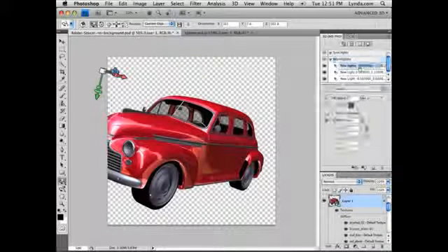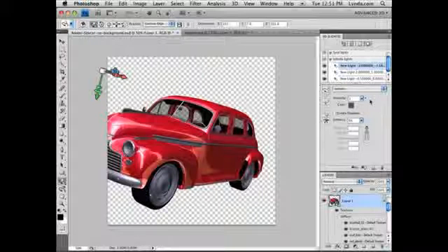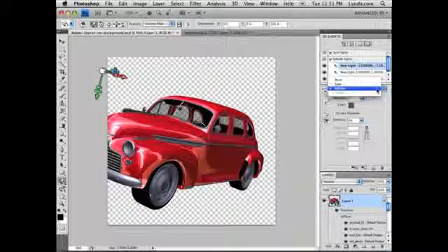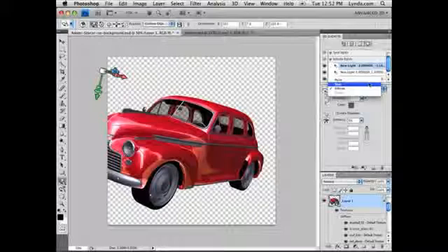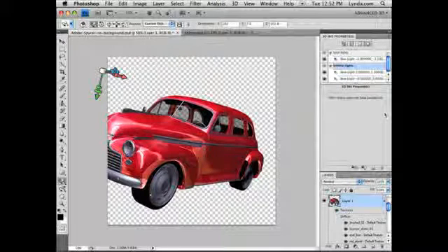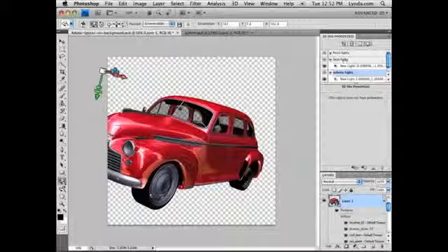Even though this light was created as an infinite light, the type of light can still be changed. To change the light's type, I'm going to select it, and then from this drop down, just change the type of light you'd like it to become. In this case, I'm going to choose Spot to change this to a spotlight. Now we can see a spotlight show up in the spotlights area here.